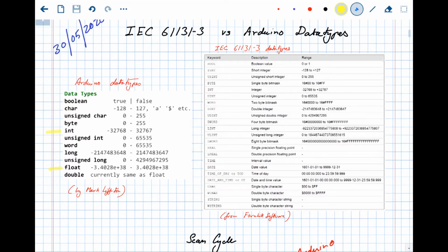Okay, in the meantime, let's shortly discuss as Paul tries to join in. Irrespective of what kind of program is being used, IEC 61131-3 discusses 5 types of programming languages. The most common of them is ladder program, obviously. Structured text is one of the best out of the 5 because it helps us write the program as we do in normal programming languages. There are other programming languages, like the instruction list, which is similar to assembly language, and then there are function block diagrams, FBDs, and so on.